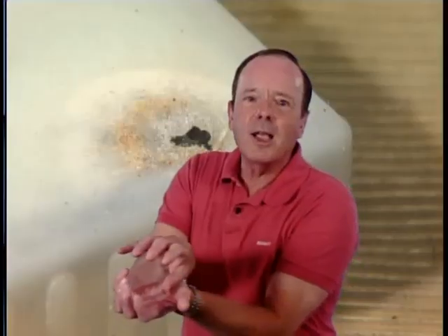First of all, NiCad batteries tend to heat up when current moves either into them or out of them. So let's assume that you've really discharged the NiCad battery. Say you had a difficult engine start, and now you're charging that battery back up. Well, it'll tend to heat up the battery when you charge it back up. Now, NiCad batteries have low internal resistance, so it allows a very high rate of charging current. And that, of course, heats up the battery further as you charge it. So you discharge it, it heats up the battery. You charge it, it heats up the battery.